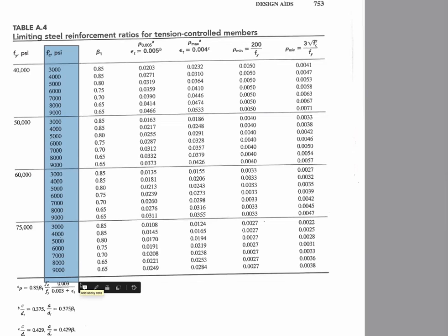As it turns out, footings are designed with relatively low strength concrete. And can anyone think why that might be? Why would you actually want to have low strength concrete in a footing as compared to a column, for instance? The footing's primary purpose is to transfer the load to the soil, and so if it's much, much stronger than whatever the soil strength is, it's kind of redundant at that point. There's a redundancy that Evan is pointing out. Any other thoughts?